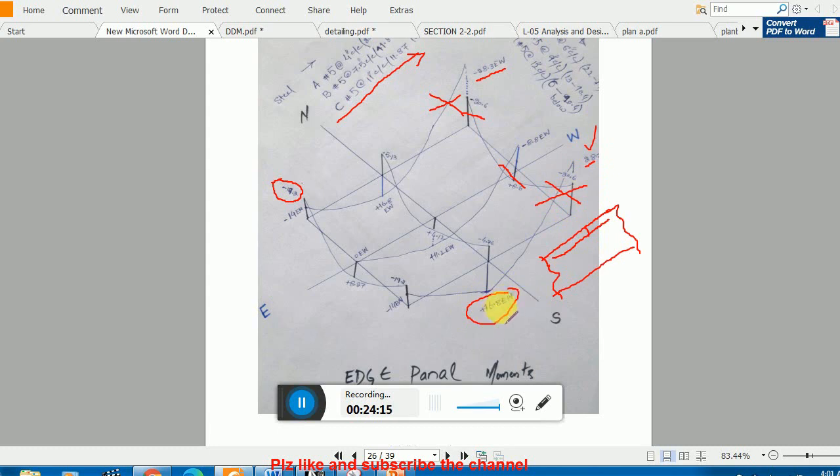Okay, now 16, this is roundabout 17. This is the maximum movement which is transferring in the longitudinal direction. So that is why I have to place bars. If I am placing here, I will place it near the bottom surface, and then the transverse bars which is coming from that direction will look like in this shape. Okay, this shape I will discuss inshallah. And similarly for this movement I have to place bar here.